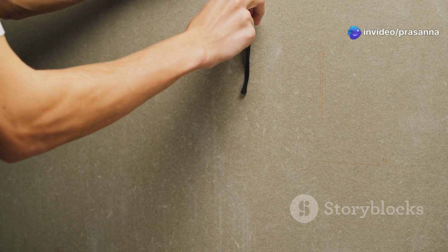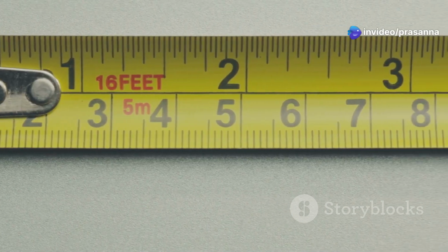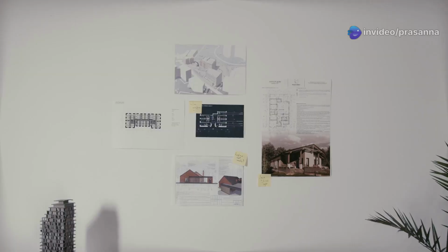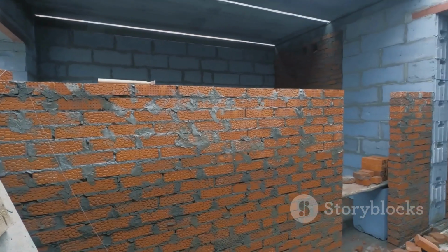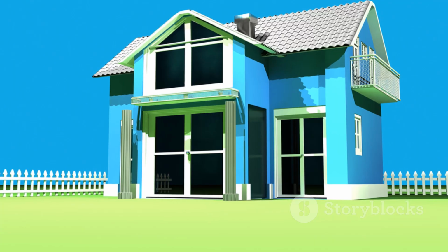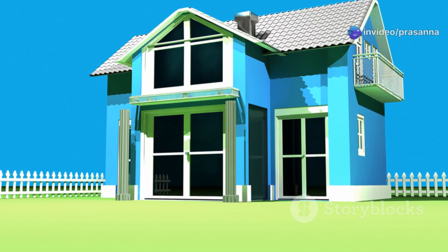You can enter the exact height for your walls. For example, you might type 3 meters or 10 feet. This instantly creates a 3-dimensional wall. Repeat this process for all the walls in your floor plan. As you raise your walls, you are creating the basic volume of your house.